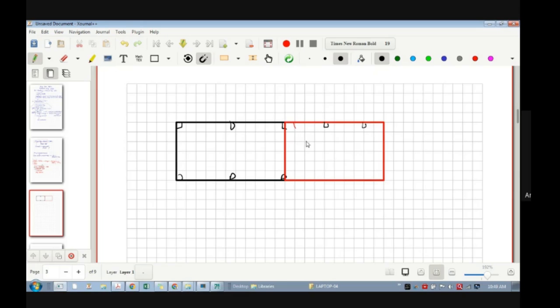This I can say horizontally it will extend. Why do I want this information? Because if this building is coming in future, then you should take additional load on this column for this building. Okay, because you know that this right side building will put additional load on these columns and these beams also, right? So if you don't consider this right side, then there will be problems for the existing building in future. So that's why we want to know, is there any horizontal expansion of the building in future?